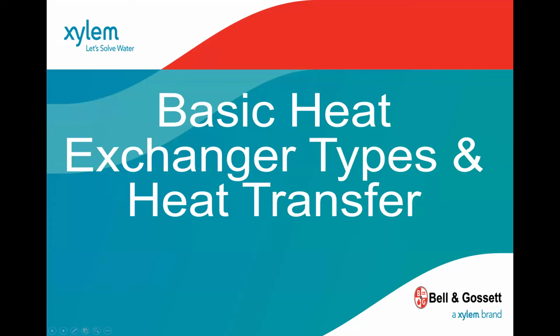I got to reformat this little section here, because I think what we need to do is probably describe the approach before listing it, because originally we started off talking about the qualities of each of the heat exchangers before describing what those qualities meant. So what they say is with a shell and tube heat exchanger, you don't generally want to make a selection that has an approach any less than 10 degrees.